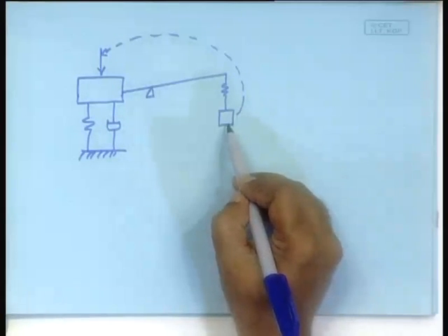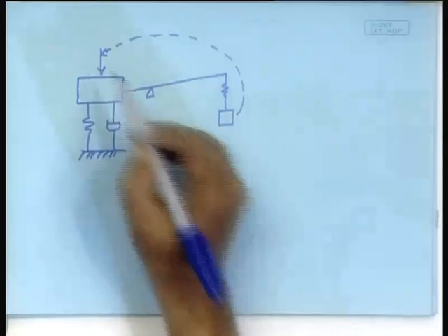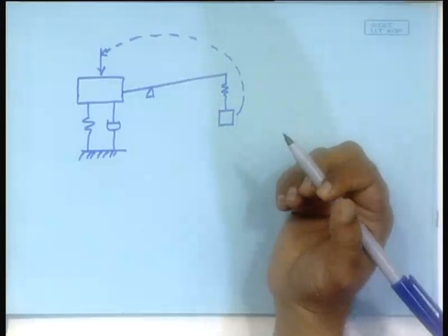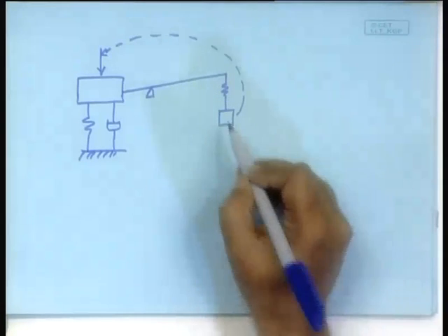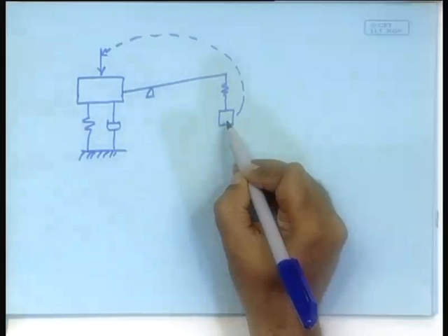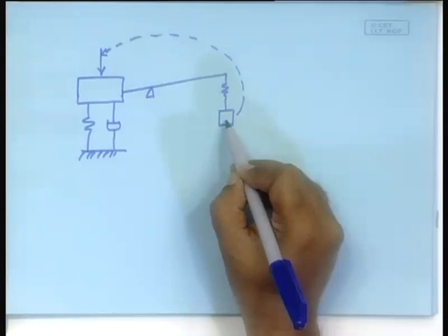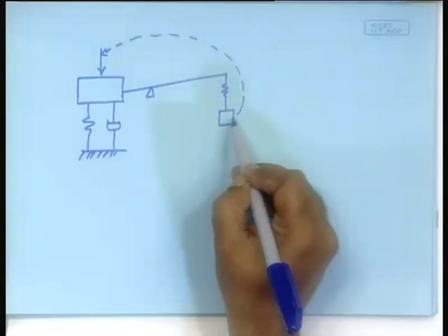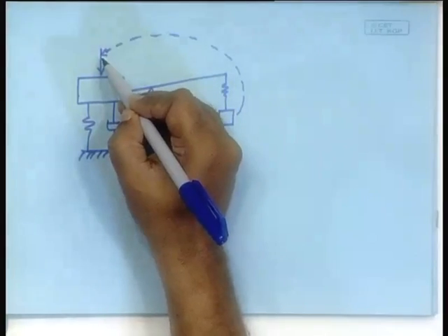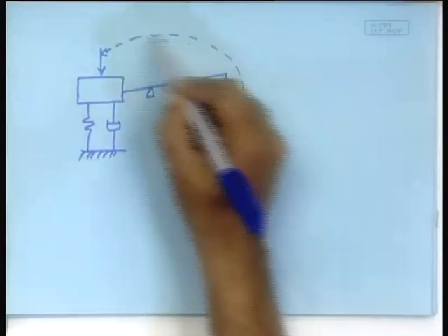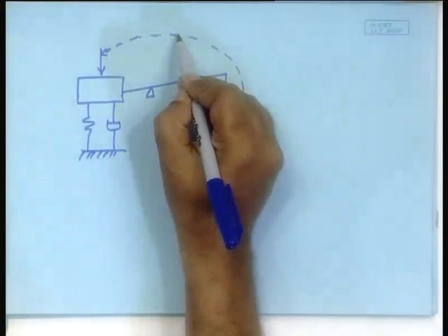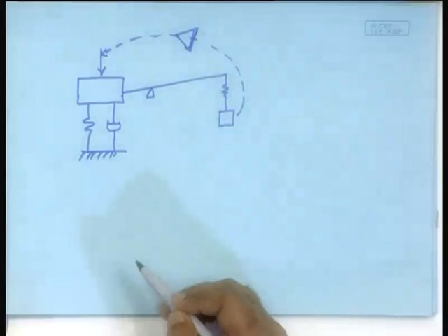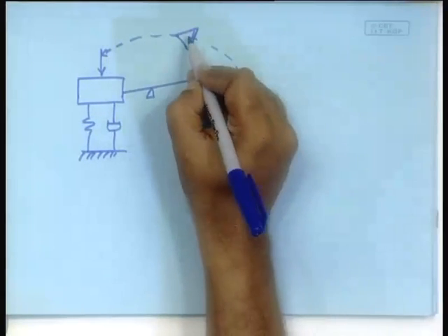Obviously, when you are measuring the position and you are controlling the force, here at this point, what is available? A flow variable. At this point, a flow variable is available. This flow is being sensed, and therefore, it has one unit. When it gets turned into a force, it has completely different unit. So, there has to be some kind of a multiplying factor, which I will represent by means of a sort of a gain, some gain block. Say the gain is alpha.